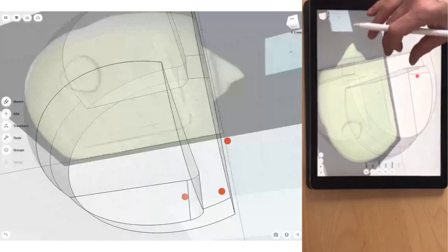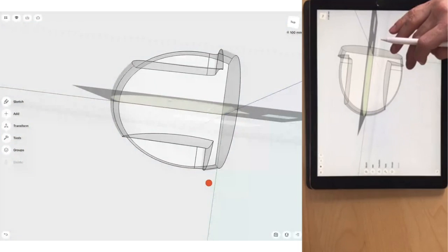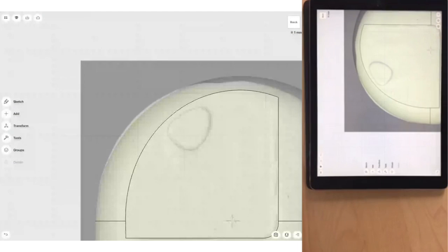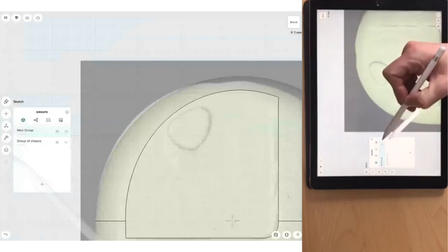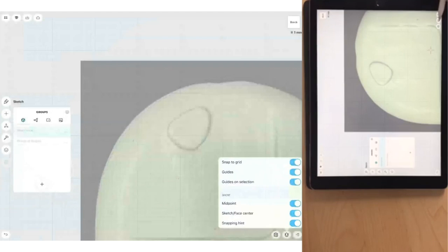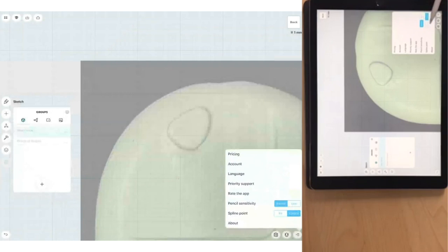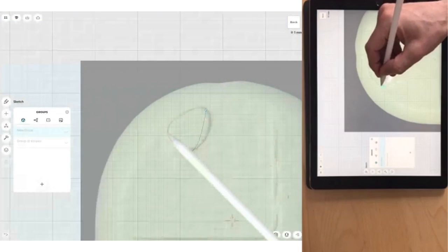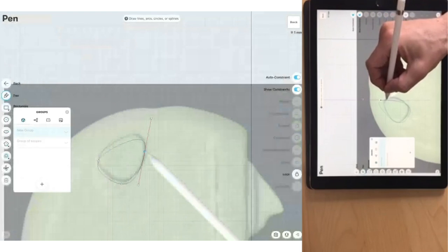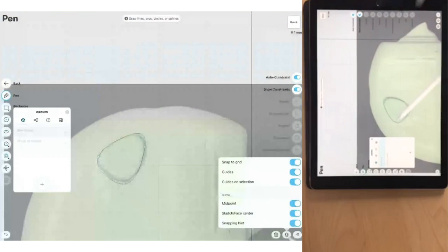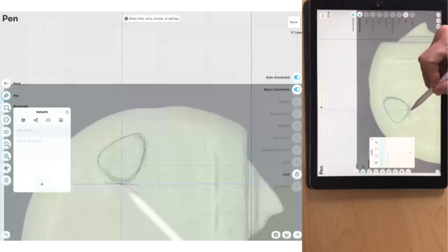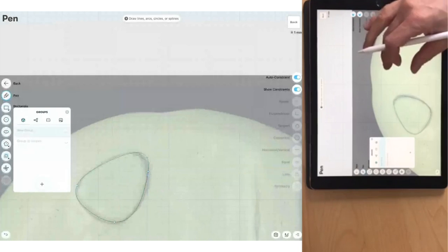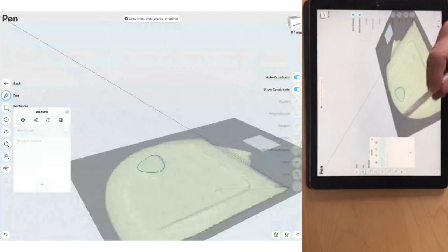Okay, so what do we do in the last 5 minutes? Maybe here. This is another nice element to show where Shaper is pretty great. So I'm going to create that shape there. I will use my fit point curve in this case. And click, drag, close this, and then I just have to adjust the position of these, turn the grid off in this case, and move this around till everything sits really well.